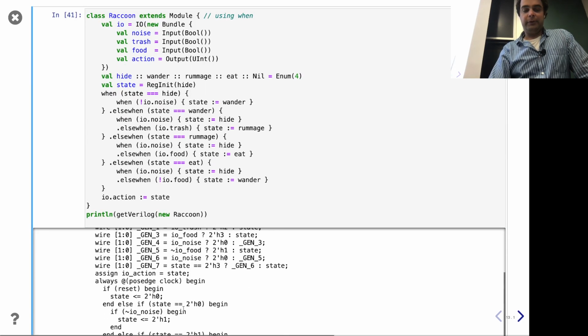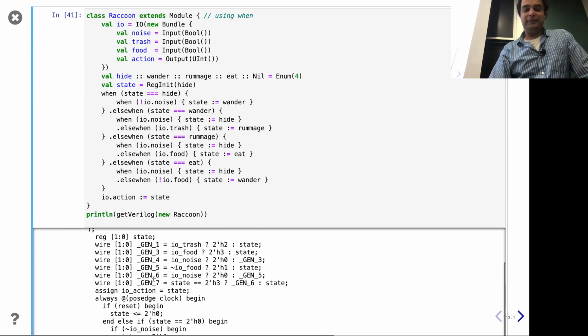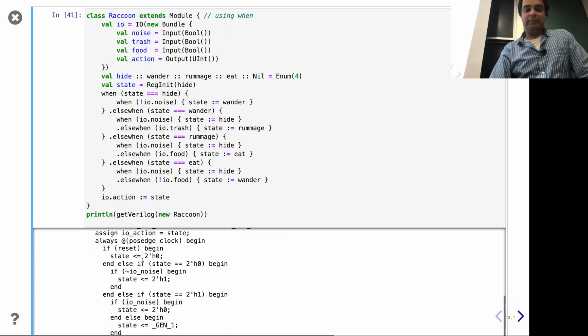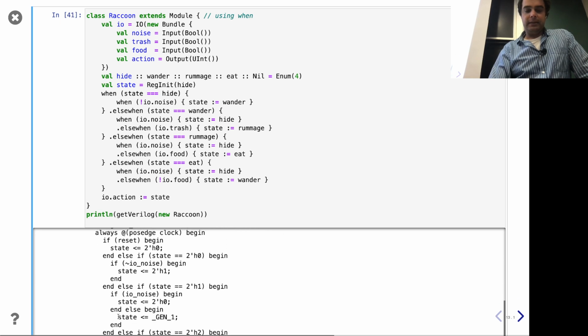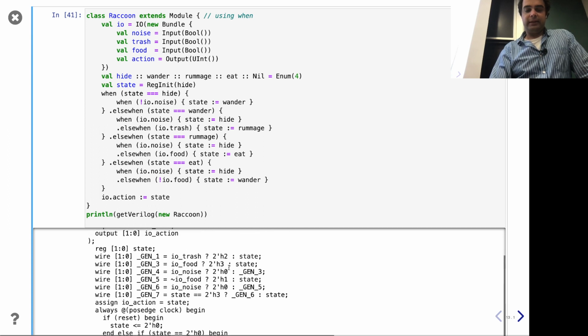It's a little bit verbose, right? You can kind of see the various things. There are these internally generated signals that it uses throughout the design, but based on the internals, it's actually filling things based on Gen 1. And what is Gen 1? Well, it's based on all the stuff over here, right? So you can see all these cases and the else ones we were talking about; these all turned into muxes, right? Is this input or something else? You can see the next state.